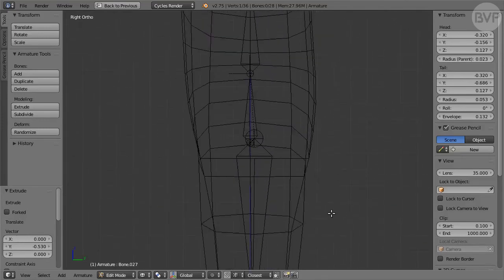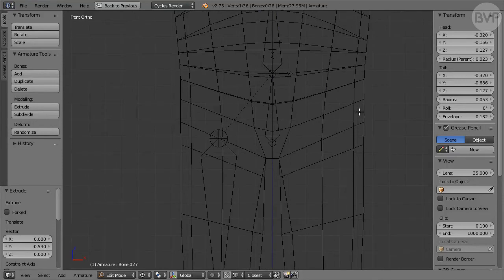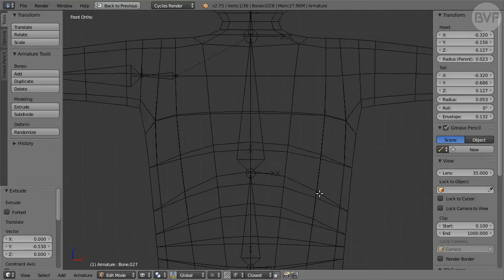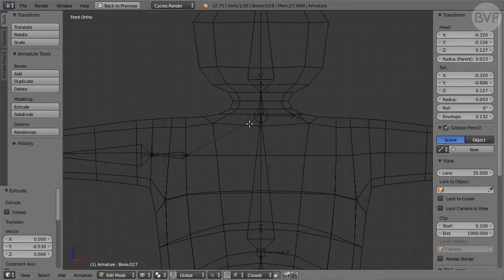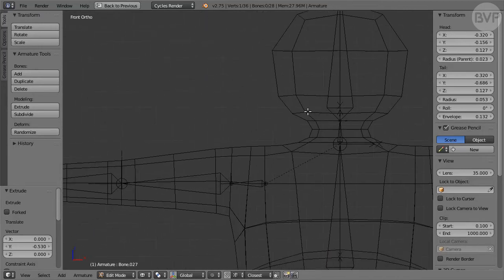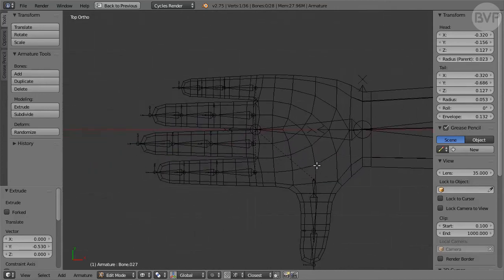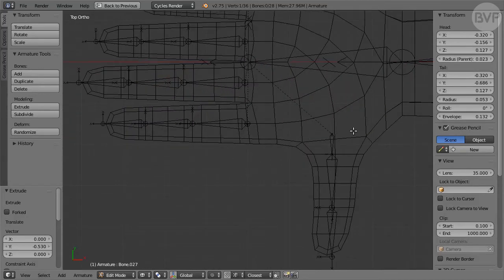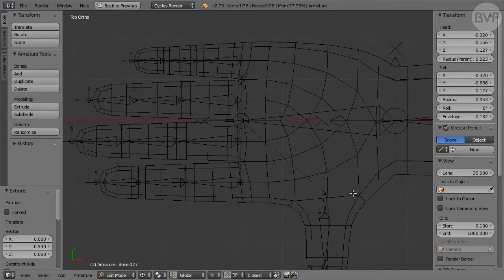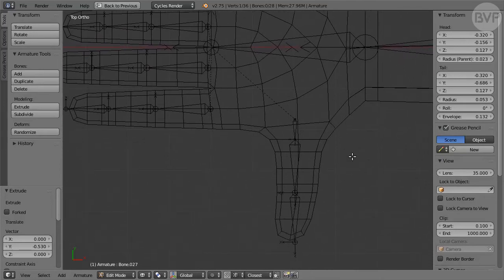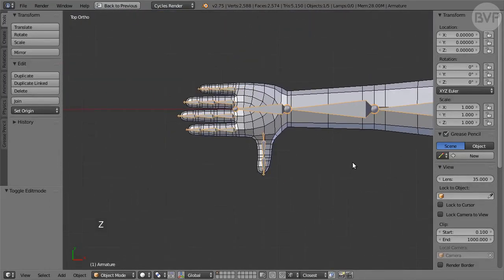We've been working with precision, but mistakes are possible. Let's check that the armature and the mesh line up correctly. Tail balls of the bones should line up with loops that define the joints. Okay, looks good. Tab to Object Mode and press Z for solid shading.